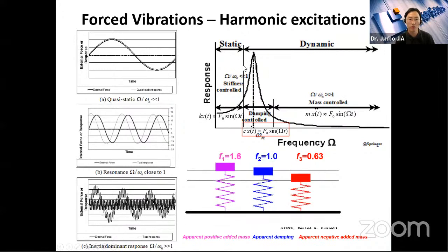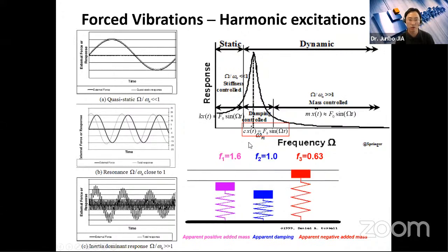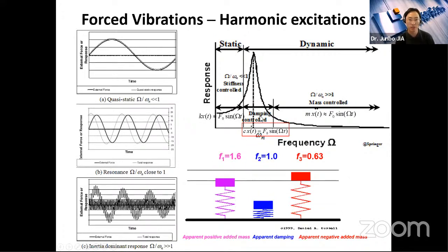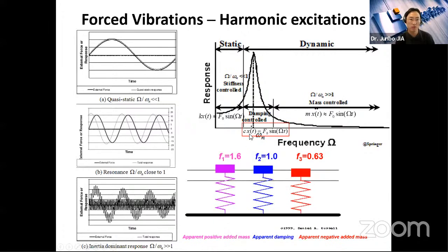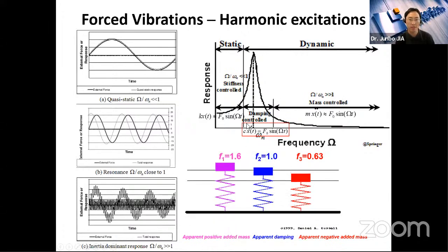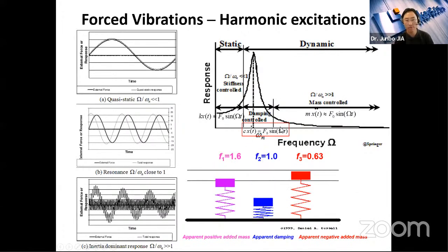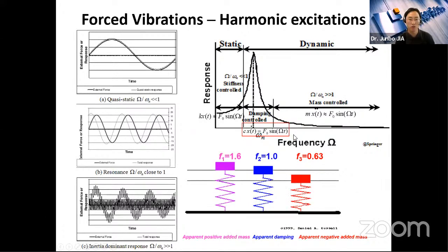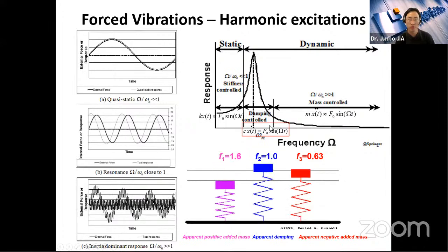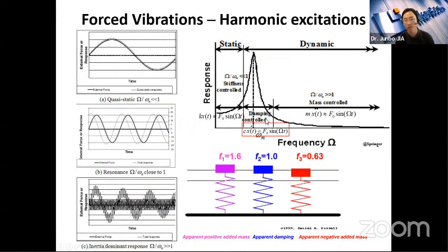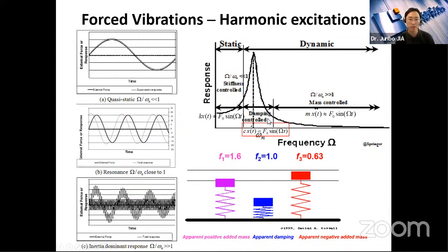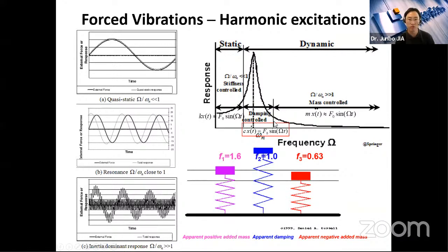So we try to avoid resonance, of course, and if there's some frequency quite close to the resonance frequency of the structure, then I have to add additional damping, for example, some external damper, in order to fulfill the relevant IAEA requirements for the nuclear power plant, especially the reactor. They are quite sensitive to vibrations.